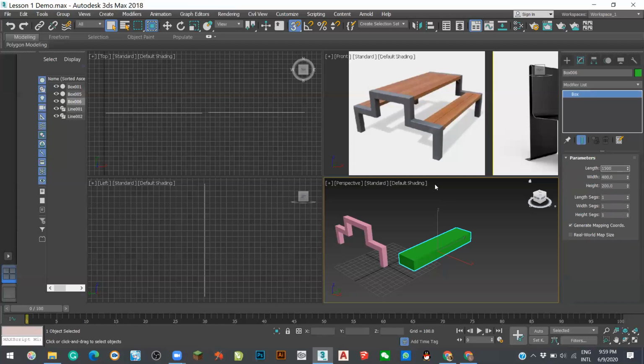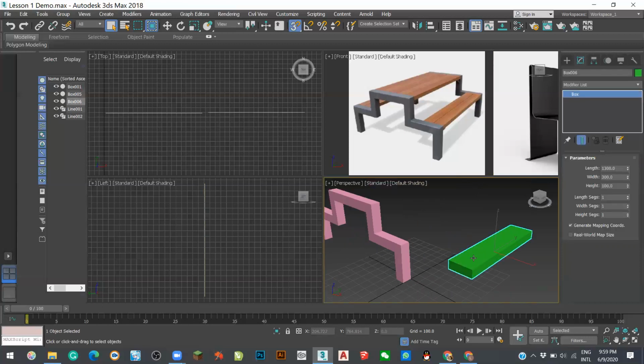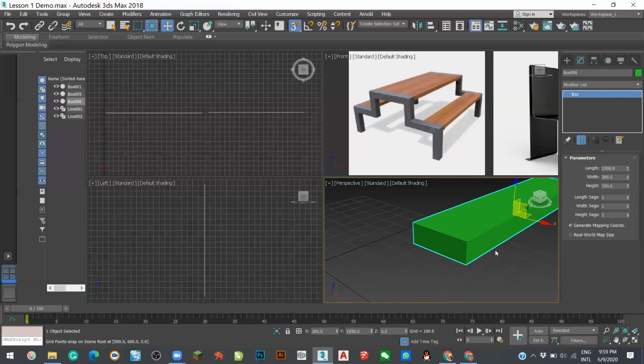Because I minus away this one 100 and the back 100, so this one will be 130, and the width will be 300, then the height will be 100. Okay. Now I click this one. I go to move, move, and S for snap. So you will see this one is already changed to the yellow button, a yellow cross, sorry.